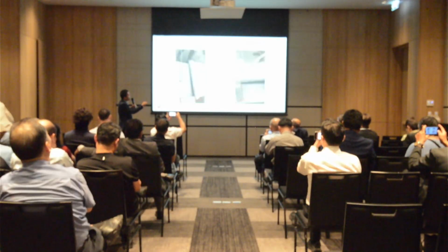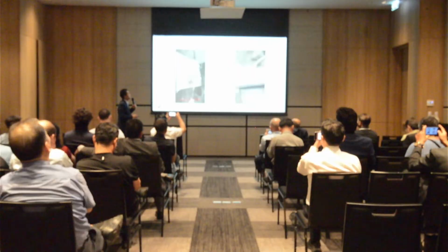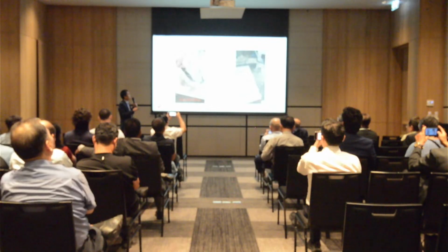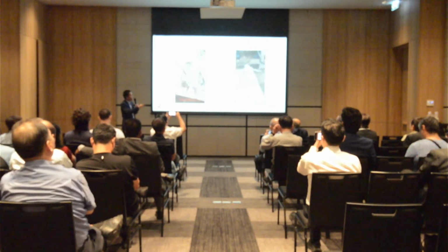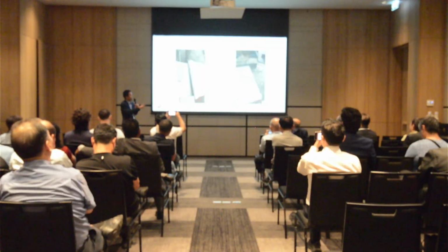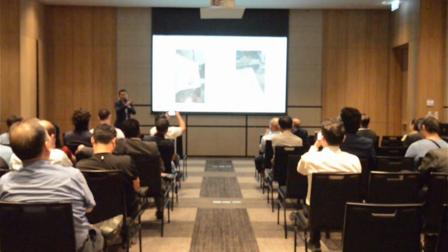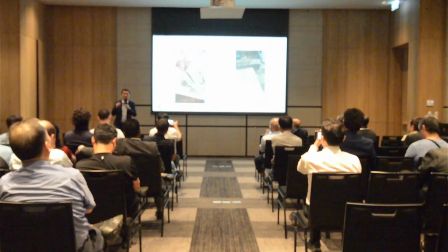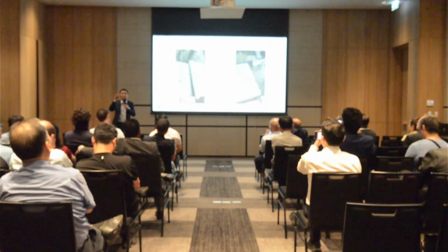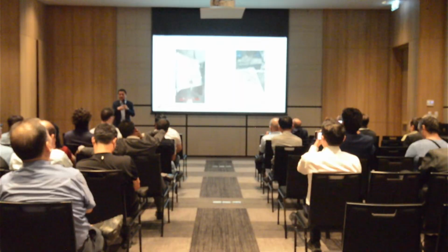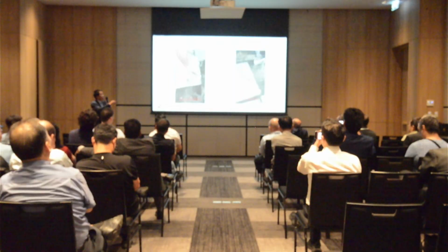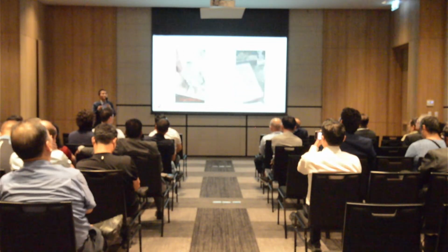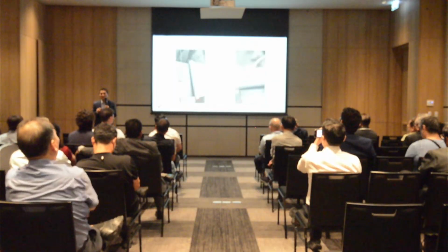And you can imagine the same alloy as a slurry, at the same temperature, is totally different. This is non-dendritic, still liquid-like, and can still flow at the same temperature. This also explains why slurry can make the part at a lower temperature, 40 Celsius lower, 620 or 610, compared to liquid. For liquid, 570 cannot flow, but for slurry, 570 can still flow. That means you can still use a lower pouring temperature to make a good part, with no misrun or non-feeding issues.